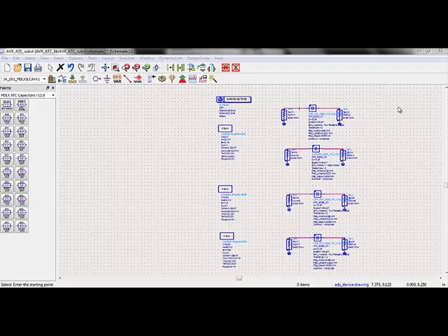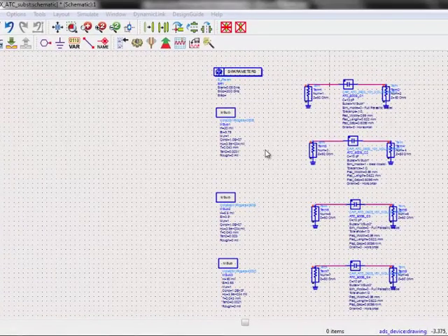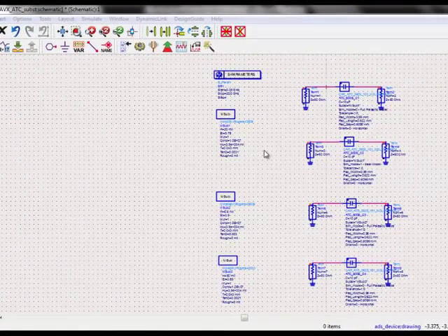We start with the same ATC capacitor model with a substrate definition of 20 mil Rogers 4350B, plus the ideal capacitor simulation as before. Now included are two additional circuits with the same parasitic model and sim mode set to 0, simulated on two different substrates, 4 mil Rogers 4350B and 60 mil Rogers 4003C.